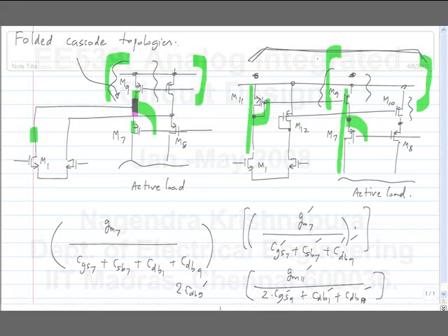Initially it was used sometimes. I mean, the idea was that you don't have to use a 1-to-1 current mirror. If you use a 1-to-n current mirror, what happens? What quantities change? Everything. No, DC gain won't change actually. DC gain will probably remain the same if you simply scale up the stages. But you have a certain signal current in the first stage. You multiply it by n times before delivering it to the load. So the unity gain frequency increases by a factor of n. But of course, you are also consuming n times more current. It's not like you are getting something for free. So you can scale up the gm of the first stage by having a current multiplier.